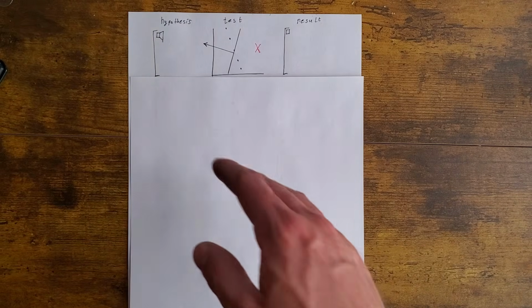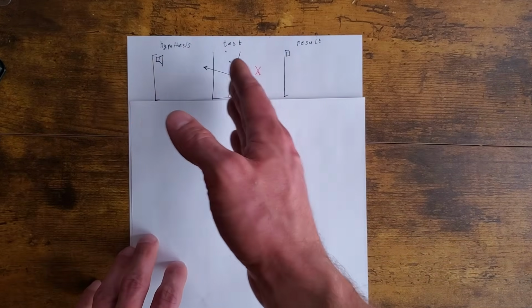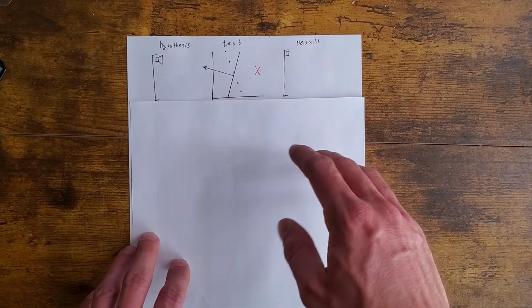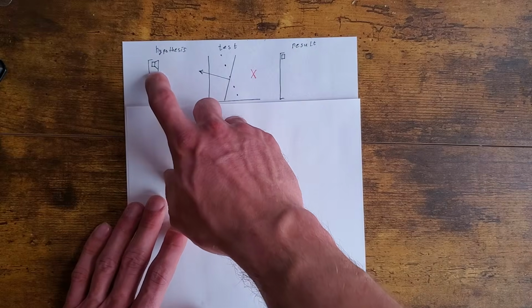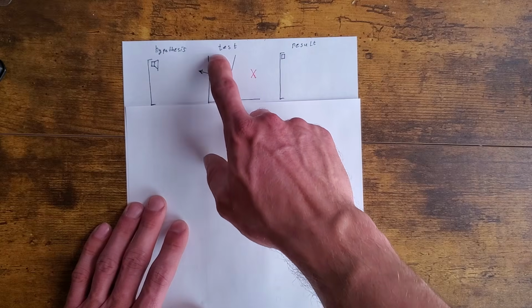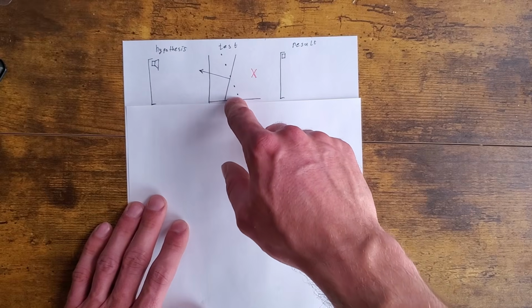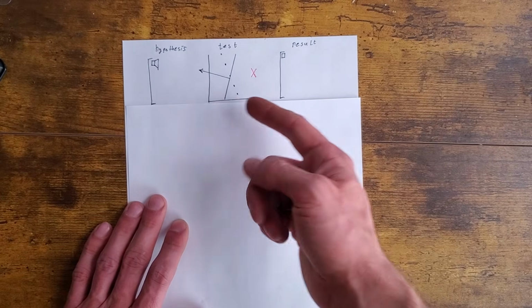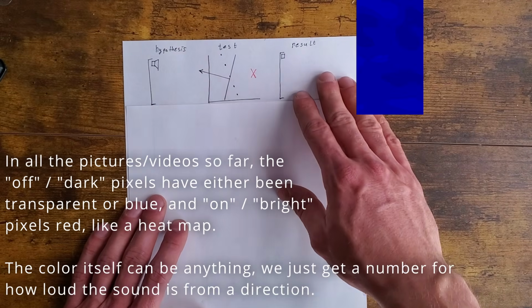The way this goes from a single direction for a single source to a full image is pretty simple too. You could think of it as sort of a hypothesis, test, and result for each pixel in the image. So we scan through pixel by pixel and hypothesize that there's a strong sound source coming from that direction. Then we draw the line that would represent that and look for sounds on that line. If there's not really anything that lines up well, like you see here, then the data doesn't really support that there's sound coming from that direction. And so this gets a low number, an off pixel, a dark pixel.